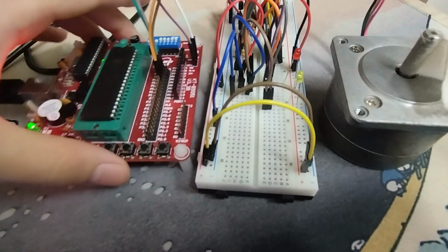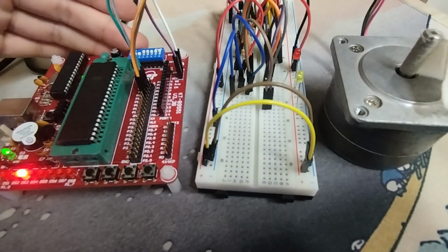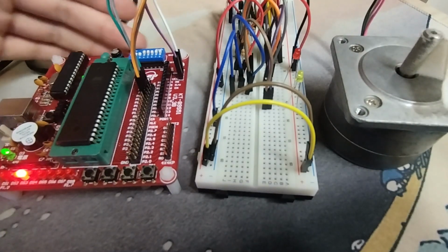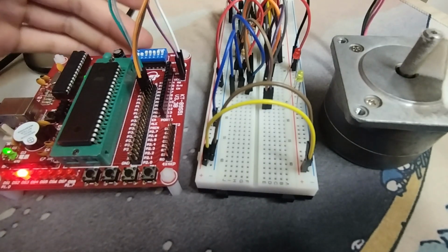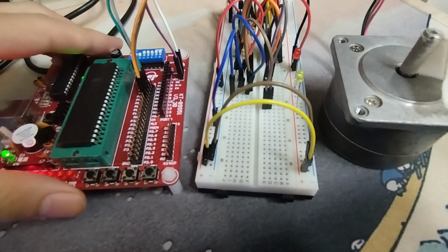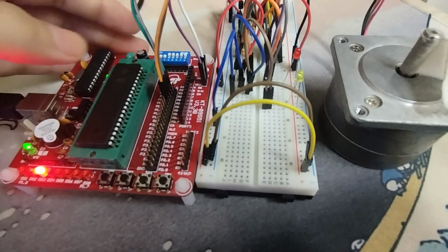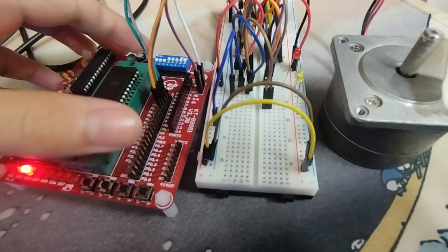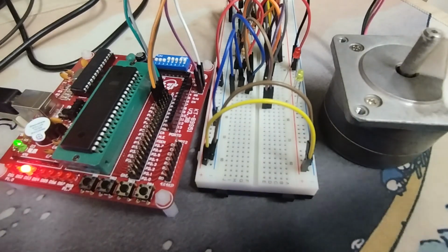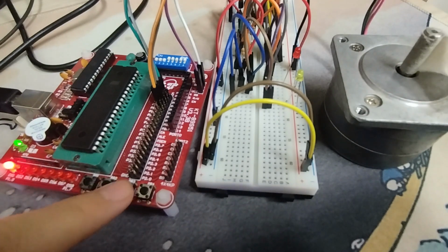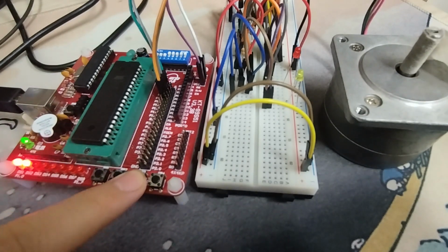And then on the top right here, we have the speed function button and the binary counter number button. So when we see right here, the on is on number 1, 2, and 3, meaning on the binary number 111. 111 on binary is 7. So when we press the third button, it will count 7 times. 4, 5, 6, 7.